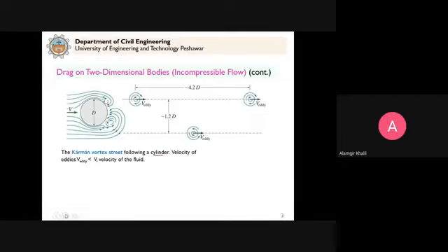Now, when this fluid flows past this cylinder of diameter d, when the Reynolds number increases, meaning the velocity increases, these vortices will form. There is a backflow, you can see here, the liquid flows in the backward direction, swirling in a rotation, and similarly on the other side also. We will discuss later what the reasons for this are.